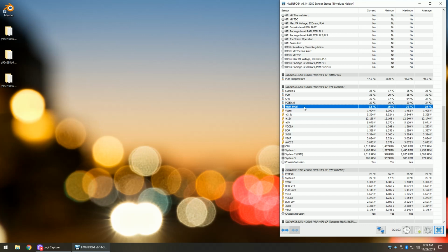A popular situation where this might get too hot is if you bought, say, an Intel Z370 motherboard, which was made for up to a 6-core processor, or designed for it, and you upgraded to, say, a 9700K or 9900K, and the motherboard may not have had a good enough voltage regulation to handle the voltage it would need to handle, say, a 9900K.